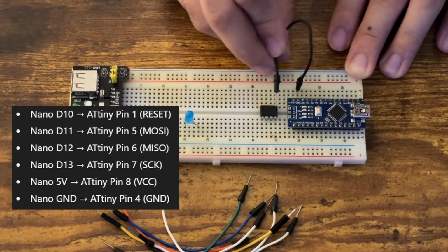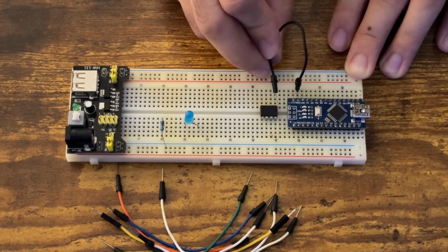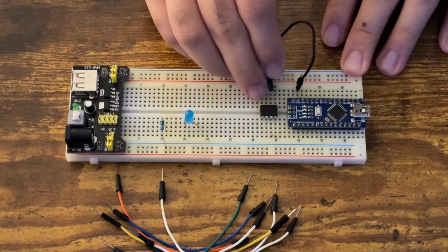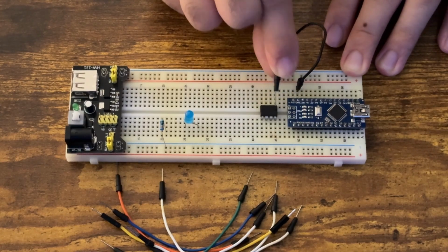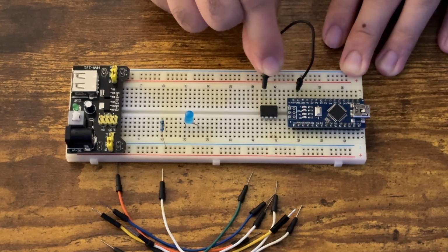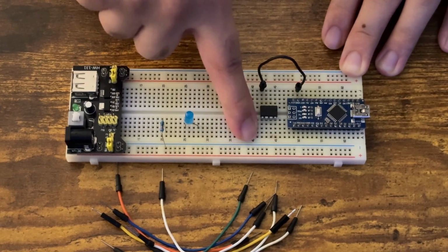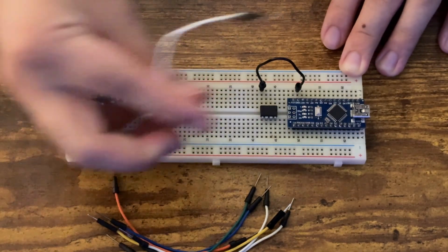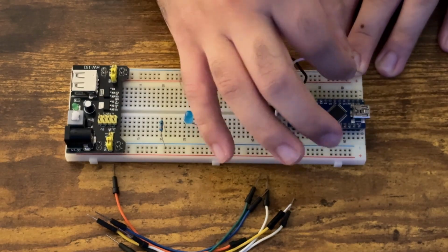Pin 1 in these kinds of chips is usually determined by a small tiny circle indent, how do you say it? The thing here. And the semicircle tells you which direction to look. So semicircle and small tiny circle here. This will be pin 1, then 2, 3, 4. And pin 5 will be on the other side, opposite to pin 4. 5, then 6, 7, 8. And pin 8 will be actually our 5 volts power.